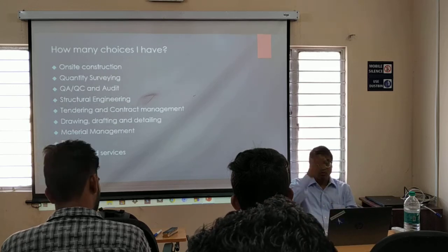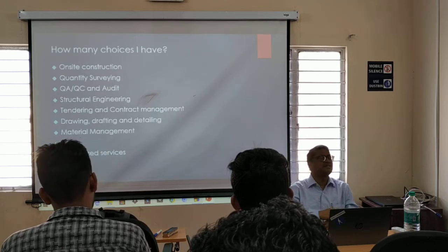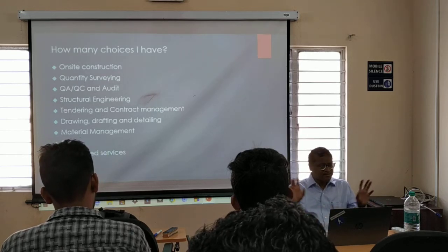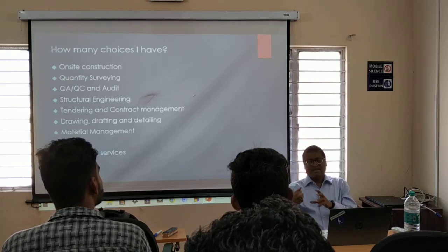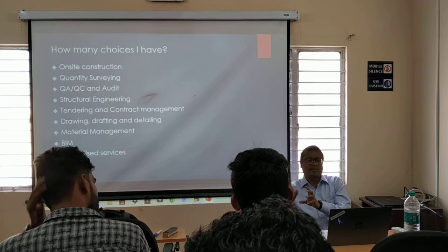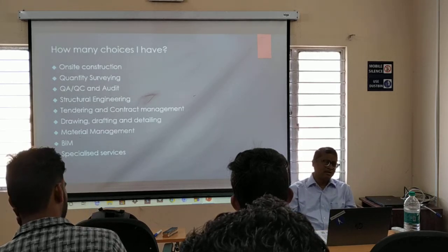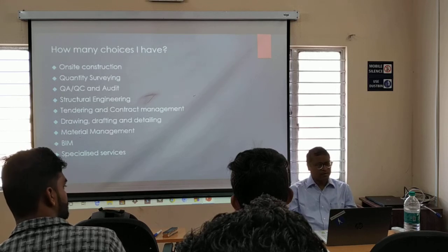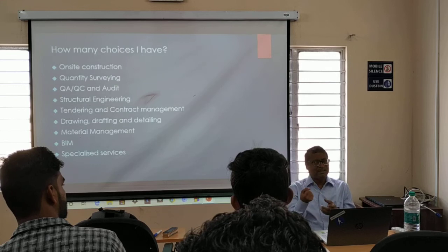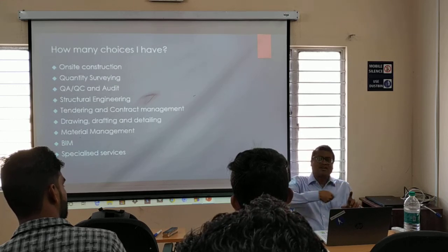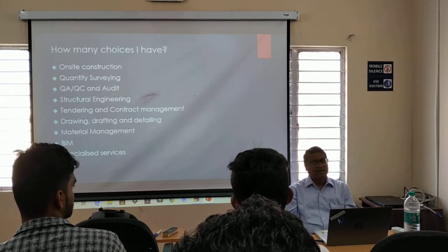They are asking about the old-style shuttering carpenter. They say the word shuttering itself is disappearing from the construction industry. It is no longer called shuttering. It was called shuttering because the carpenter used to choose the wood, the type of wood, wooden planks, casuarina props and all. Now it is no longer used. Even in small towns, you see that they are using plastic-coated plywoods. And for that, the only cutting tool is the circular saw, hand saw, machine. They are cutting only with machines.